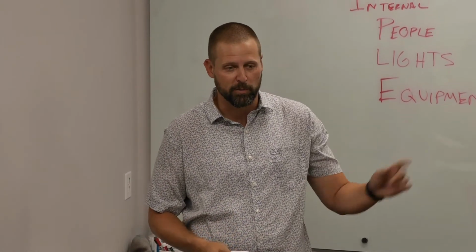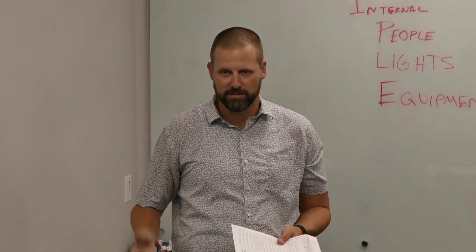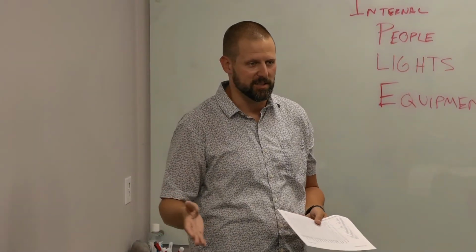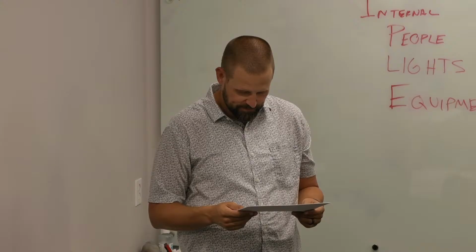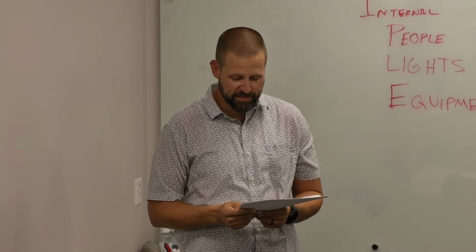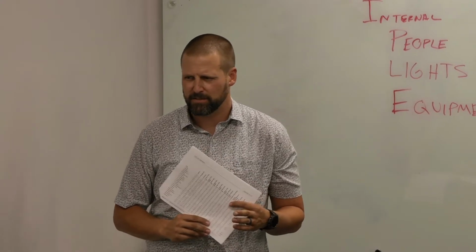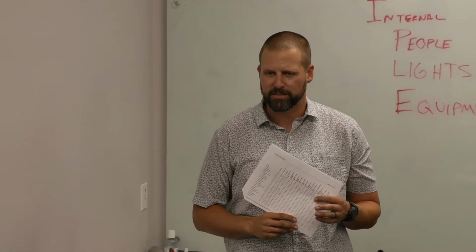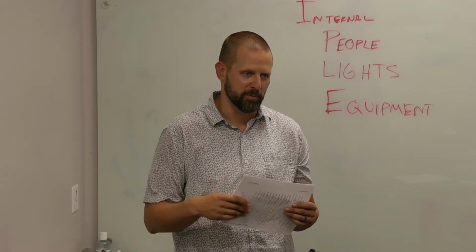Okay, so critical 0.1%. Other buildings, there's a ratchet. You can use anywhere from 0.5 to 2%, depending how critical it is. Design wet bulb is how we design towers. We talked about towers in here. Cooling towers use evaporative cooling, so the limit on what your tower can hit is determined by the wet bulb.